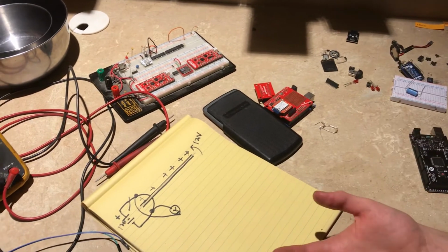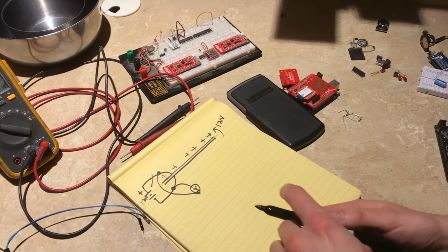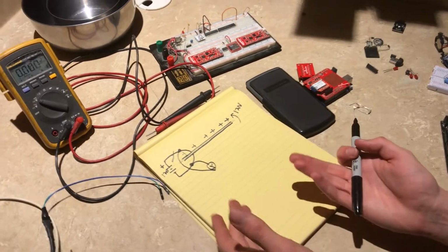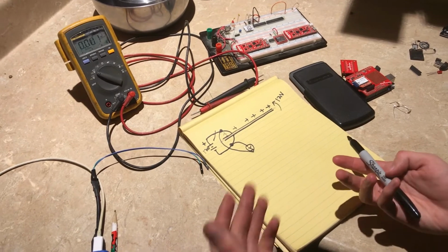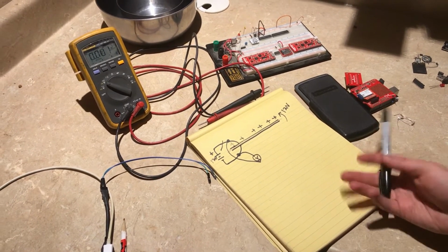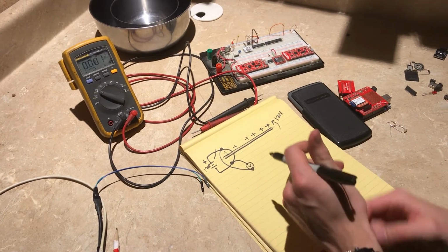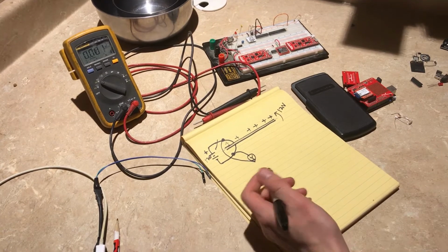But ideally, if you were to charge up a capacitor and not measure it, it would sit at whatever voltage you charged it to indefinitely. But that won't happen because it's the real world, and we'll have things just kind of leaking off and dissipating. And if you measure it, that will drop the voltage even more.